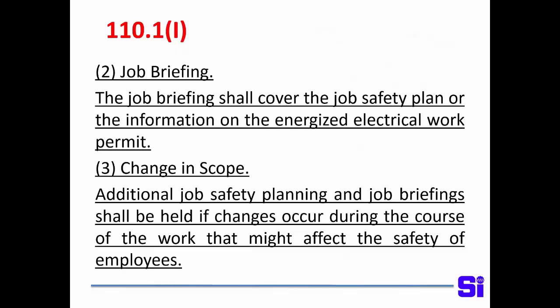And according to the OSHA report, when they were removing the shutter, a grounded metal part of the shutter fell down and made contact with an energized stab on this 15 kV breaker. Now, you're only maybe 100 feet, 200 feet from a generator. So the short circuit current is tremendous at that point.